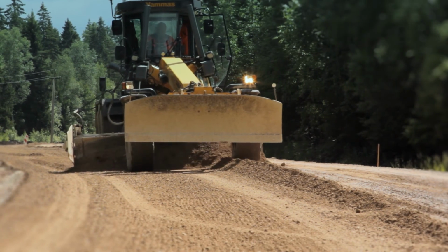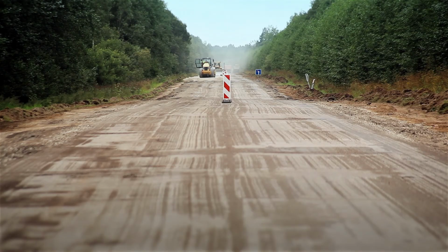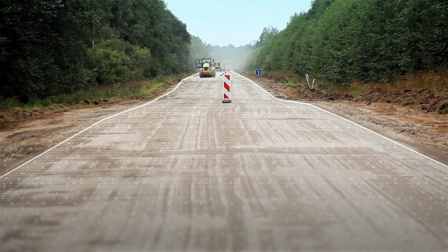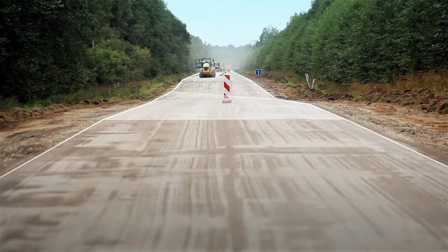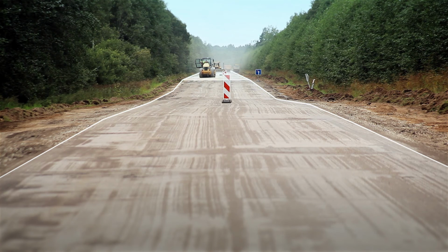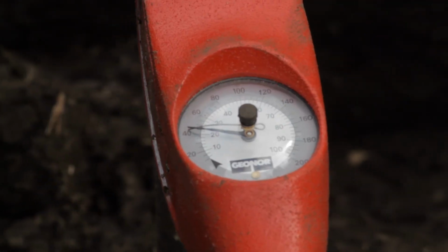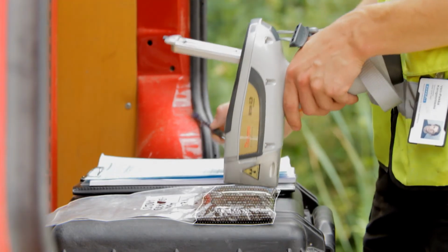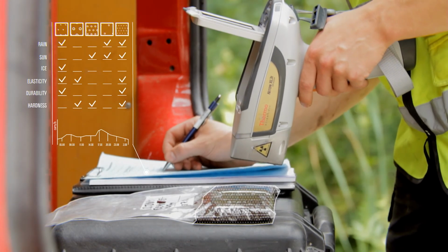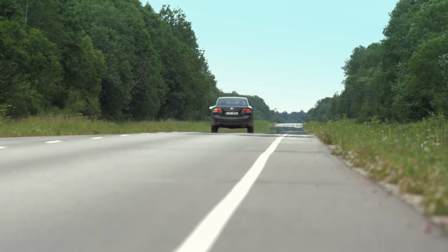Processed road sections were covered with a temporary gravel layer and opened for traffic. During the 8-month period, the ash injected into the subsoil reacted with the peaty subsoil, while the road section obtained the required hardness. After 6 months, the temporary surface layer was removed, and the reconstructed road section was covered with a permanent, hard surface. The measurements were continued on both test sections even after the works were finished in order to observe any possible change in the quality of the roads. The results showed that the road surface which was stabilized with the oil shale ash was resistant and reliable.